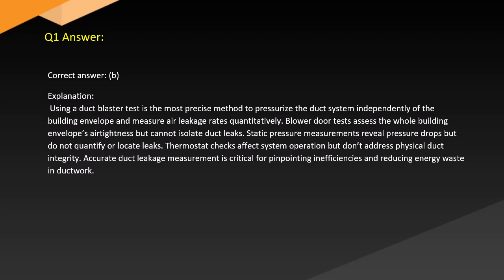Blower door tests assess the whole building envelope's air tightness but cannot isolate duct leaks. Static pressure measurements reveal pressure drops but do not quantify or locate leaks. Thermostat checks affect system operation but don't address duct integrity. Accurate duct leakage measurement is critical for pinpointing inefficiencies and reducing energy waste in ductwork.